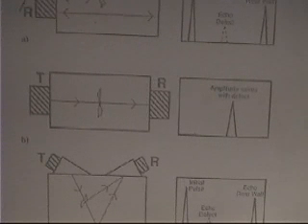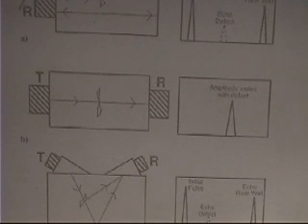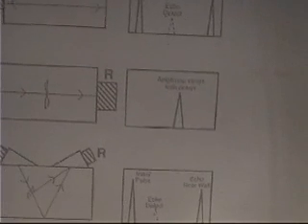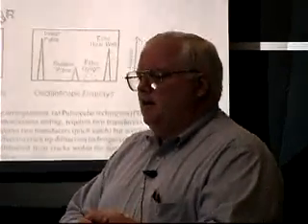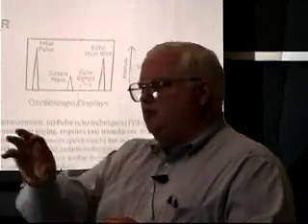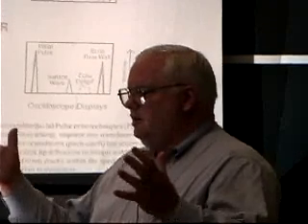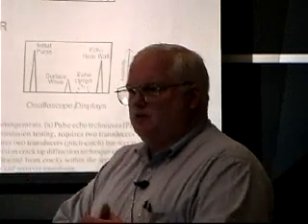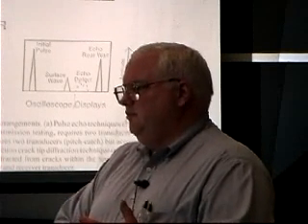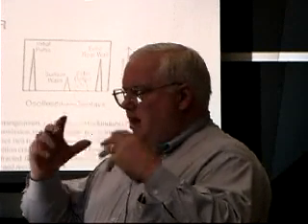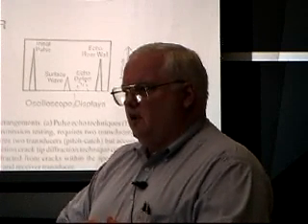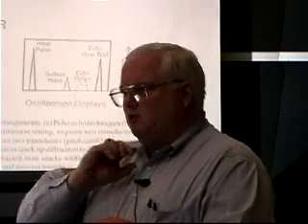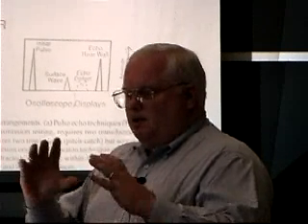I remember once a pipeline company, they send what they call pigs down the pipeline every 5 to 10 years. A pig is nothing more than a little conveyor that you put in the pipeline, and the fluid going through the pipeline carries this thing down through the pipeline. The little conveyor has got all kinds of non-destructive test equipment on it, typically eddy current type of detectors. And it has a big recorder on it, and it will record the data for the next 10 miles or 20 miles or whatever, as the fluid, whether it's gas or liquid, is pushing this thing through the pipeline. And they call these things pigs.